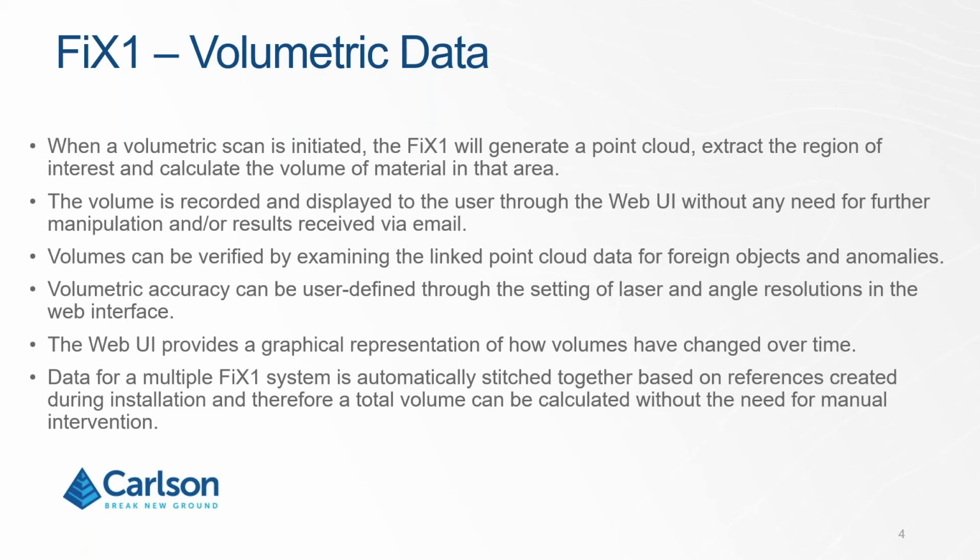Volumes can be verified by examining the linked point cloud data for foreign objects and anomalies. So if you do see something weird or an odd volume that does come out, you can interrogate the web UI and take a look at that particular scan. Volumetric accuracy can be user-defined through the setting of the laser and angular resolutions in the web interface. We'll talk about that more later.